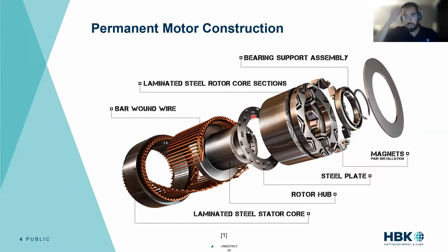So let's start with just a motor construction. This will definitely be background and already known for a lot of you, but I think for some of you, it might be a new topic. So in the motor, we only have a handful of components. We have a stator that has laminated steel that's pressed together. In that laminated steel, we have a series of windings, and we can see these copper windings that are touching each other in many circumstances and going around the machine. We have bearings. That's kind of a failure point. I think that would be no surprise.